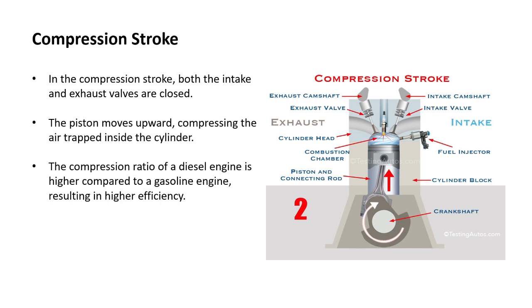We compress the air as the piston moves up and we are injecting fuel. You will see that there are some lines coming in here. This is supposed to represent atomized diesel fuel. We will inject the atomized fuel into the combustion phase, and because of the massive increase in pressure, there is also a corresponding increase in temperature.